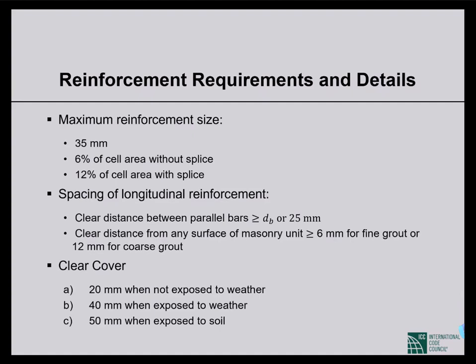Now some requirements for reinforcement. The first one is maximum reinforcement size. We can go for quite a large diameter rebar. 35 millimeter is the maximum reinforcement size that we can use, so quite large.